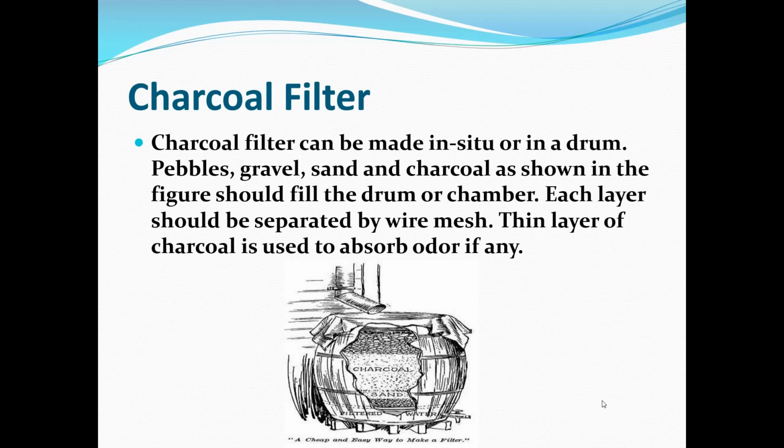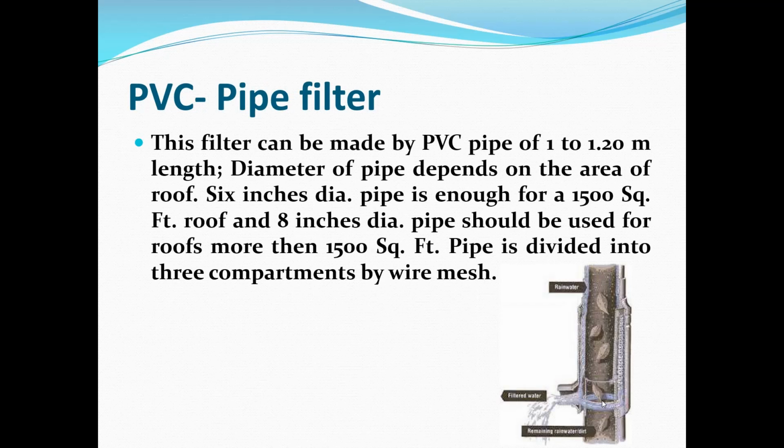Then the charcoal filter. It can be made in situ or in a drum. Pebbles, gravel, sand, and charcoal, as shown in the figure, can be arranged, and each layer should be separated by wire mesh. A thin layer of charcoal is used to absorb odor, if any.